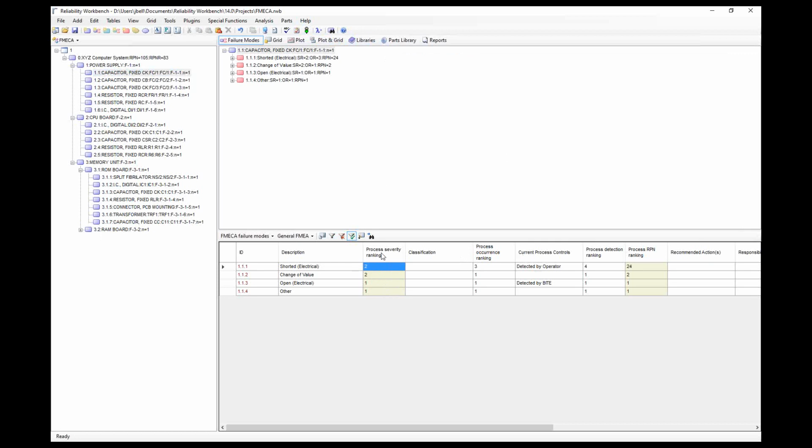And then the FMEA, the failure modes, are ranked by their RPN value, the risk priority number, the RPN, which is just simply the product of these 3 values, the 3 rankings. So that way we can rank the different failure modes. The ones with the high RPNs are more severe or are worst case failure modes, the ones that we want to maybe take mitigating actions or redesign around those failure modes. You can see this one's a little easier to do than a MIL 1629 style FMECA. It doesn't require the hard numbers, it's more estimates on these 1 to 10 estimates in these 3 ranked categories.